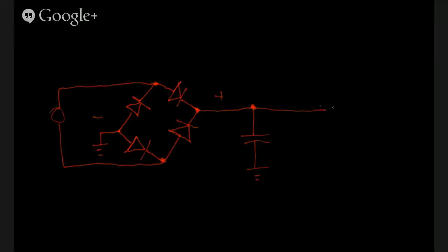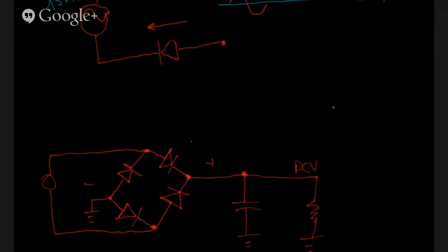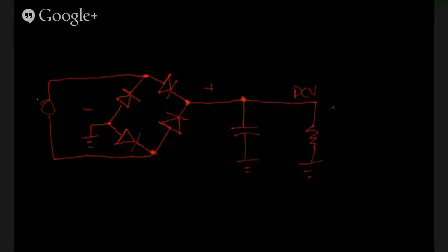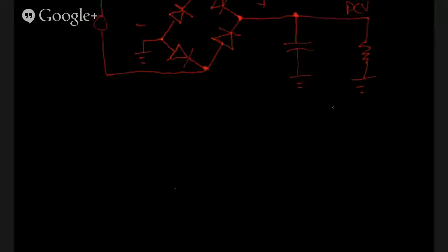And then we'll have a DC voltage available here, which we can then put through a load of some sort. This is our AC. So normally on this side we'd have a transformer. I don't know if we talked about transformers. Yeah, transformers only work on alternating current. Yeah, we'll cover transformers. Be able to make a power supply by the end of this.